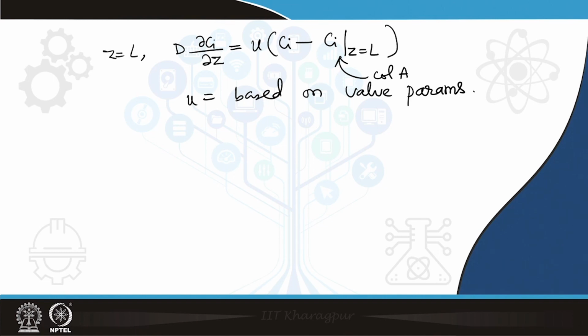So, I think this is a very nice discussion on the modeling of pressure swing adsorption, and this model framework can be quite useful to find the optimum cycle times. For example, to understand how the concentration changes during the startup phase, or how the concentration varies with time. So, what should be the optimum cycle time, and what should be the optimum pressure given the equilibrium or isotherm conditions. This will finally lead to effective design optimization of these setups. So, both from the operational as well as the design perspectives, the model results can be very useful.